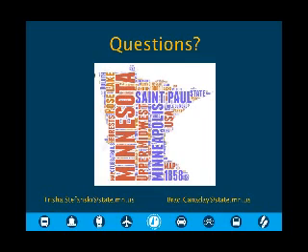But if you're going to get something that's less than 5/100 of a foot, you can use the RTK to get your XY because it's really tight, at least here in Minnesota. But the vertical is always the problem. So we actually used total station instruments coming off of our geodetic benchmarks and control work and actually leveled through each of those to get an elevation that's down to the 100th or 200th of a foot accuracy. So using that for the targets. It's the only way that you're going to get something less than 5/100 of a foot when you scan.